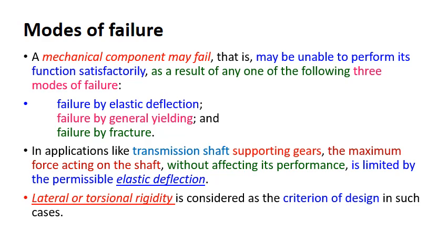If it is subjected to only bending, we will look into flexural rigidity, that is EI. So we must select materials with high values of EI or GJ. For every failure mode, we will have a corresponding governing design criterion. That is actually your mechanical property, so that is where we have to look.